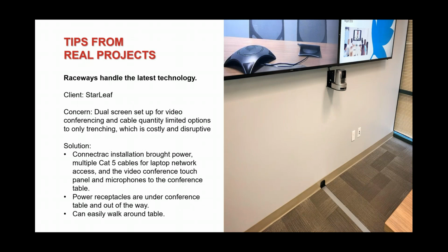Raceways also can handle the latest technology. One of the questions I get often is, "How do I put my data in here? I've got a great system, will it interfere with it?" Because raceways are required to have separation with the data cabling, there is not an issue. ConnectRack actually puts our power in a steel flexible conduit, so it can lay right next to it.